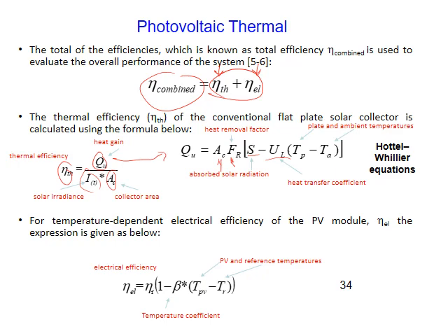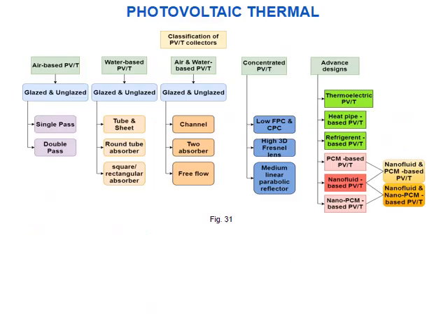Okay, for electrical efficiency, we discussed it before, we can calculate the output to the input power, or we can use this formula, the relative efficiency here, and this is the temperature coefficient, and these are the PV and reference temperature of the cell.